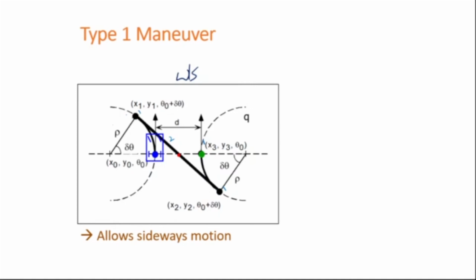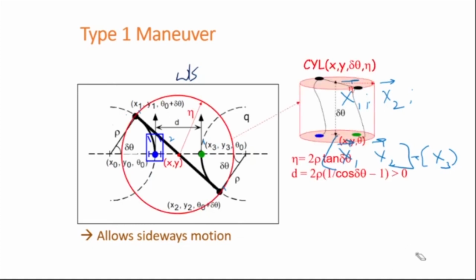And we are able to prove it by showing that if it has a set of vector fields like this, we can use Lie brackets and then generate other vector fields, x1 and x2. We'll give you a third one, x3, which can be in some other direction, can be sideways. Now this is mathematically showing us that the car can actually go and park sideways using Lie brackets. Now in terms of an algorithm, how do you make the car go and park sideways? That is what is more interesting to us.